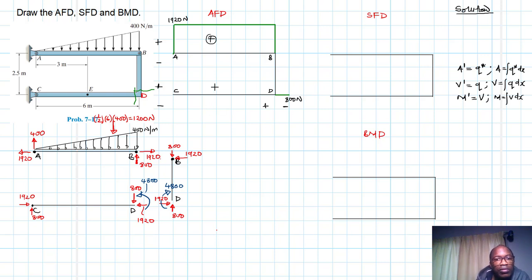Great. And then from there, we don't have any axial distributed force from D to B, axial like so. This is the axial distributed force I'm talking about. So we don't have that, and therefore the slope of our axial diagram is just going to be equal to 0. So it will just be a straight line from D to B like so, and when it reaches B, the sign changes there, which adds up algebraically, which simply means our beam has finally closed.